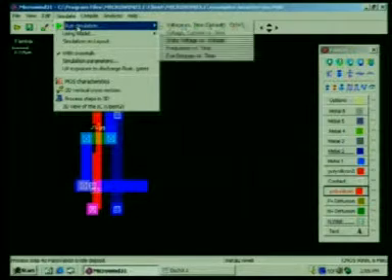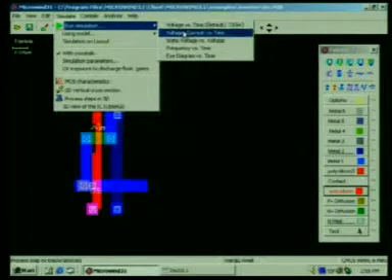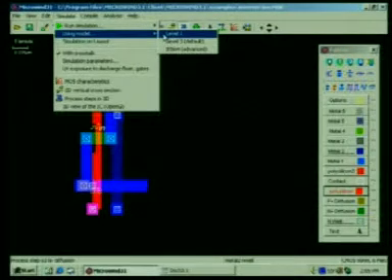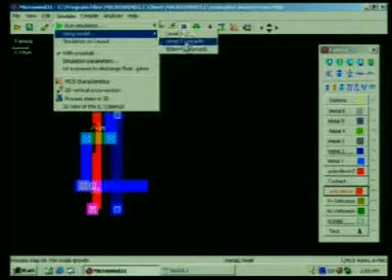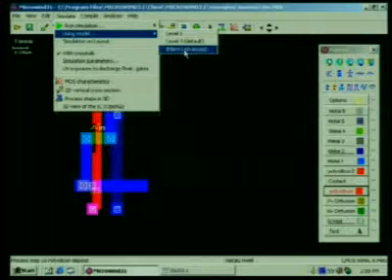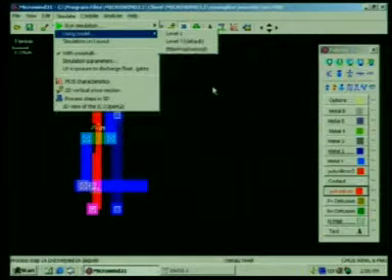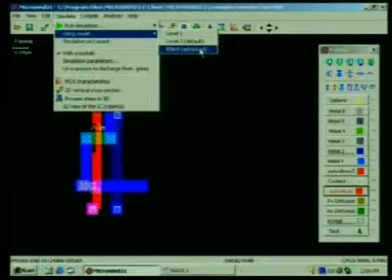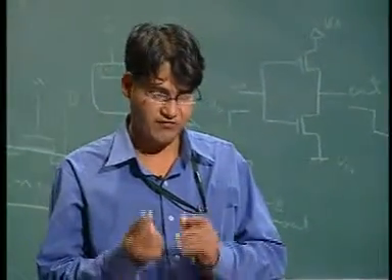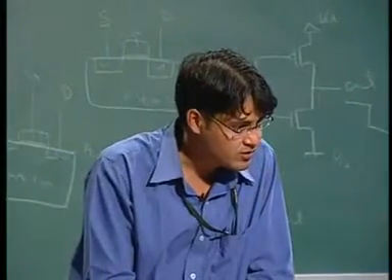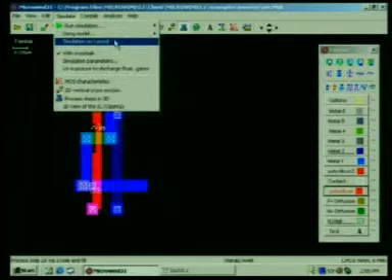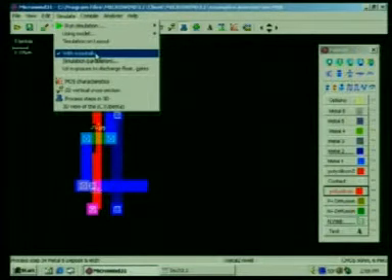And there are different kinds of simulation, you can open any of these windows using models. I have already explained the level 1, level 3 and BSIM 4 models. These are different models according to the parameters, like BSIM 4 is the advanced model, it contains 300 parameters. For this there is a module, Pro Tutor, which even provides those parameters. You can edit the parameters and check the effect on the characteristic curves. So in this way you can simulate using whatever model you want. For the simulation on layout, I will take one example, with crosstalk and without crosstalk, meaning the interference effect. You have to analyze both and take the worst case.